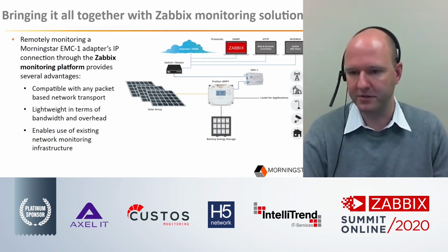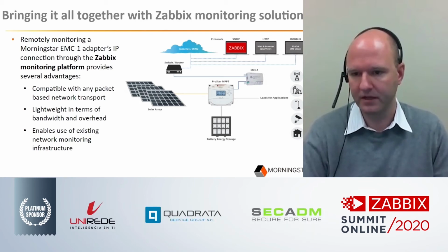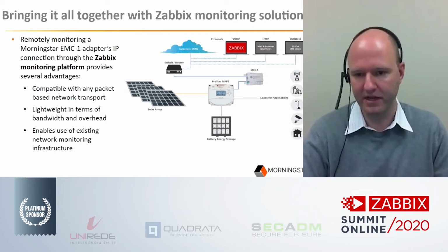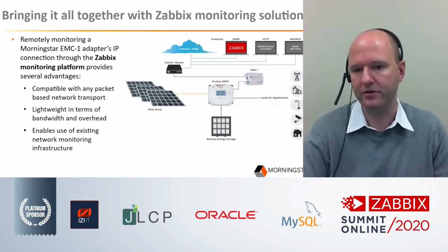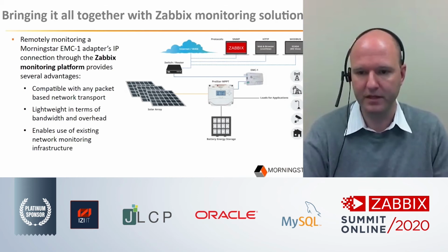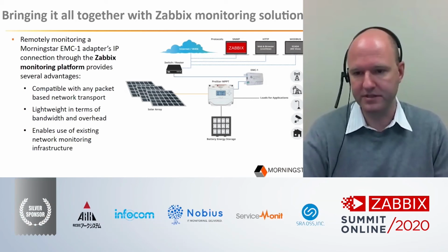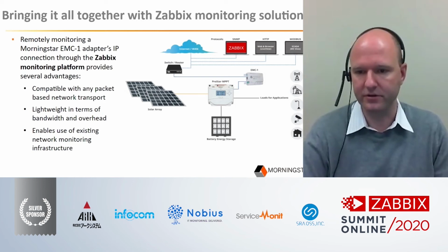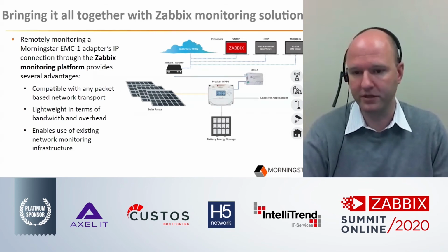You can use simple HTTP or HTML web pages to get a simple look at a dashboard to understand what's going on in the system. And of course, when you implement SNMP, such as we have with the partnership with Zabbix, then SNMP can be used alongside the network monitoring software, and the Zabbix network monitoring software can be enabled to monitor the entire site with just one tool. And being cloud-based or server-based can have great applications for energy storage, data logging, notifications and alarms, and of course, a database, either native or external in the cloud, can be used to archive the large amounts of data that will be accumulated.